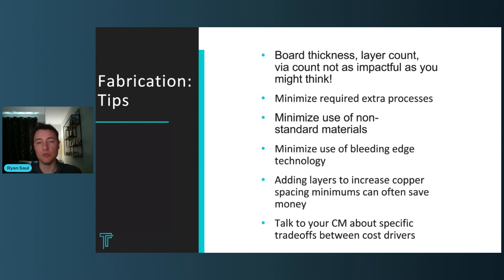There's no consumable drill bit that's going to be impacted by the number of drills you're doing. They're all going to end up being copper filled and plated flat, so they can be drilled directly into pad. They're tighter registration tolerance. The annular rings can be smaller. I'm a huge fan of laser drilling. And so if laser drilling can solve your problem, that's usually a good idea.